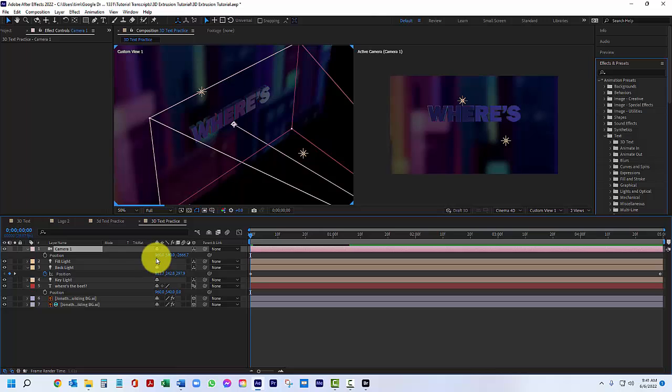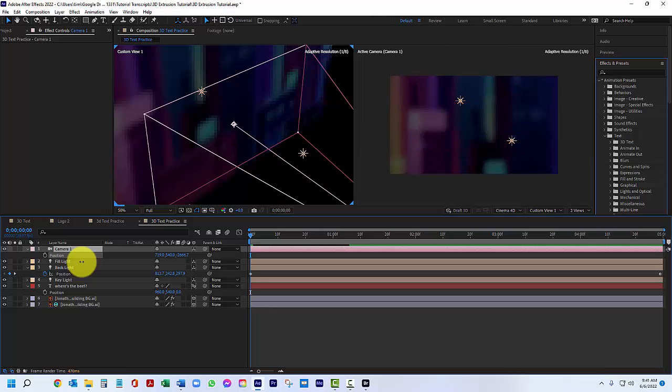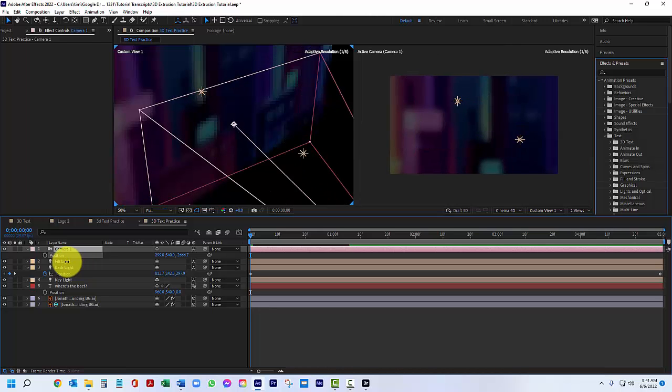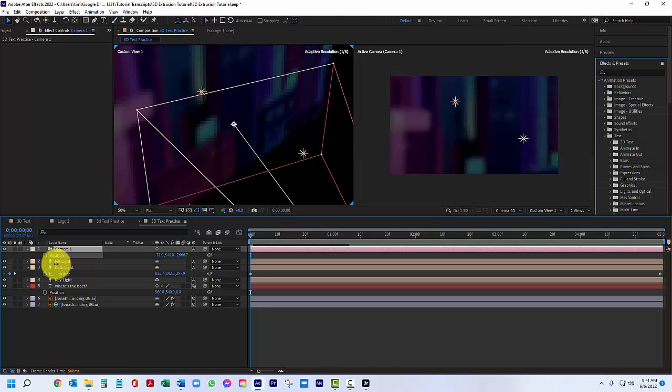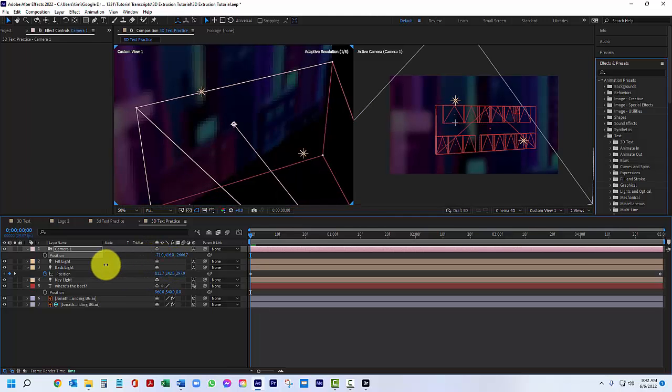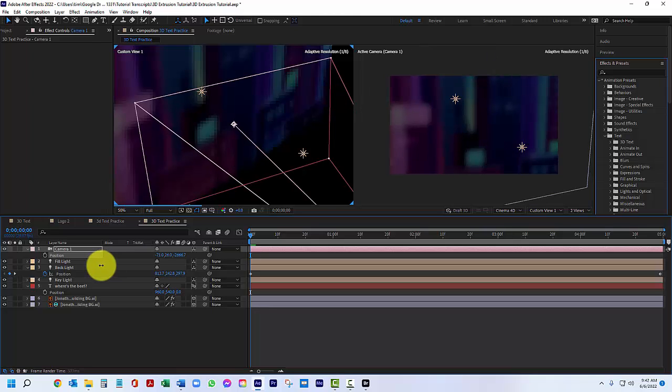And let's bring the camera over to the left. I'm holding the shift key here. I don't want to go too far because I don't want to see the edges. If you start to see the edges over here, you've panned the camera too far. And I'm going to bring it up a little bit so that we've got a little higher view. Again, watch your edges. Make sure you're not getting too close to the edges over here. We can see how close we are in the lower corner.